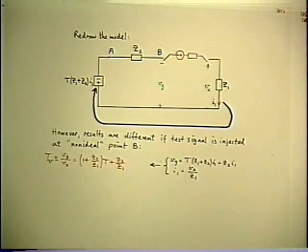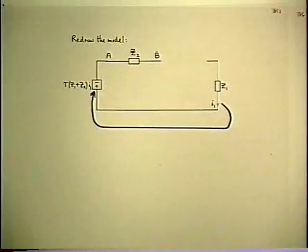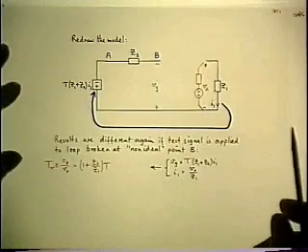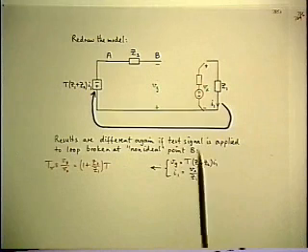Well, you might say now, well, that's too bad that the signal injection technique didn't work. If you can't get to an ideal point, maybe we'll have to back up and go to the original method, which is breaking the loop and applying a test signal. And we'll have to give up the benefits of not breaking the loop, but if we can get the right answer that way, maybe we have to anyway. So let's see what happens if you break the loop at a non-ideal point and apply the test signal. So that's sort of back to the original method.